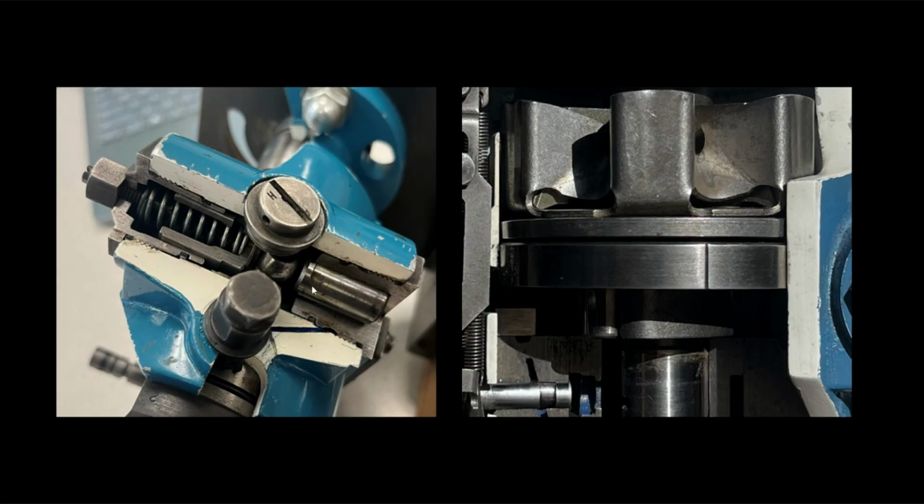Here it is again. Higher transfer pressures due to increased engine speeds push on this pin against the tension of the spring. In doing so, the timing mark on this camring can be seen moving in the opposite direction of pump rotation. Since the injection pump travels at half the speed of the crankshaft, the amount of timing advance at the injection pump doubles at the crankshaft. For example, if we advance the timing at the pump about 2 degrees, the timing advance at the crankshaft would be seen at 4 degrees.